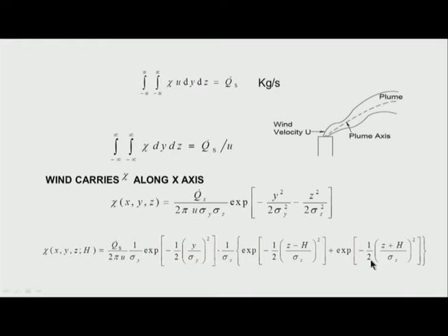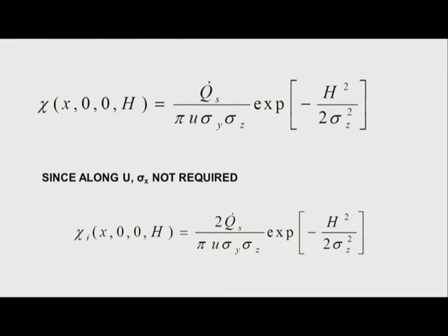And this is how we calculate the different values. All we have done is shift the problem from trying to solve the diffusion equation to trying to find the value of the standard deviation y and standard deviation z. These are all experimentally determined and can be determined quite well, and tables are available. I will come back to this.